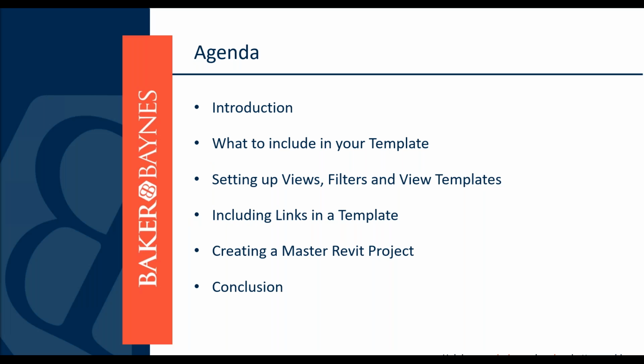Okay, so if we just quickly look at our agenda for today, we will start with a basic introduction to Revit templates. Basically, why do we need them and where to start planning and preparing for them. Then we will look at the typical content of a template and which standards to include, and also continue with some important steps such as your view setup, filters, and also view templates.